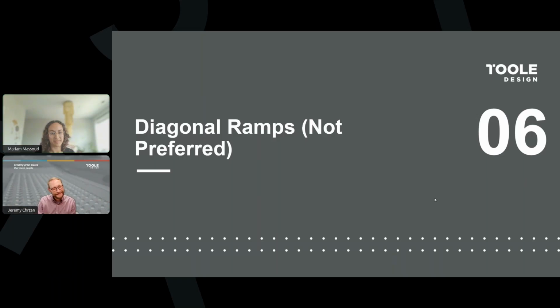So if the profile grade of a street is 4%, is it allowable to match this slope at the bottom of the ramp where the cross slope will be at 4% in this case where it meets the pavement? So this is relating to the longitudinal slope along a curb line, and do you need to alter the slope at the crosswalk location? And this relates to the required slopes within crosswalks.